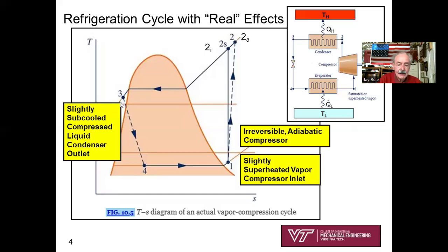So all we need to know for a real cycle is about how much subcooling is going on from the saturation temperature of the refrigerant down to T3. And so we'd simply look up H sub F at T3. And amazingly, that covers the three subtle points about analyzing what we'd call a real refrigeration cycle compared to the ideal refrigeration cycle.